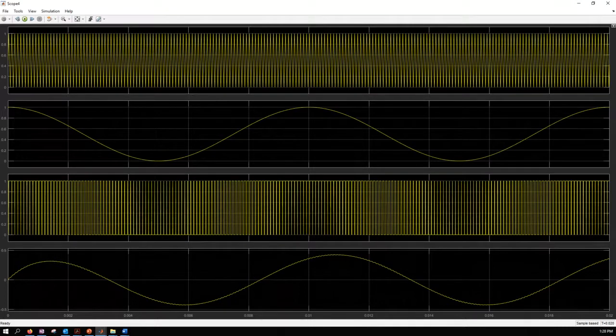And once it passes through, we can see that the current has a nice sinusoidal shape. Of course, there's going to be somewhat of a phase shift between the voltage and the current because of the inductive lag. There's an inductive lag that results in a slight phase shift, which is true for any machine. In certain cases, we tend to compensate for that, and we can talk about that later. And now let's zoom in a little bit. I want to see what is actually happening here.